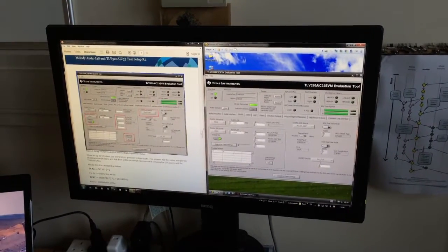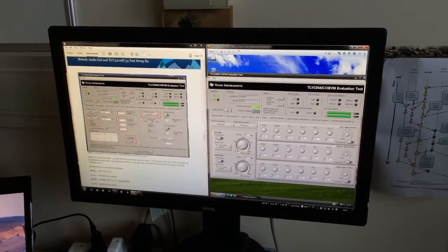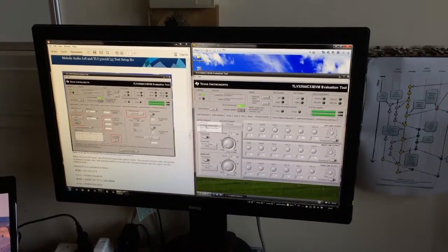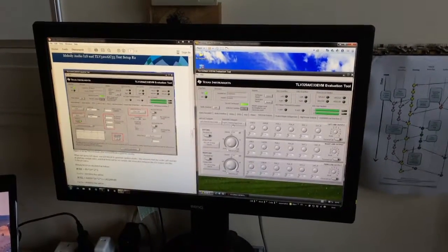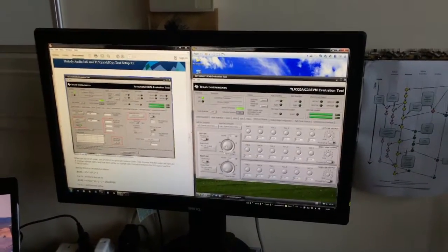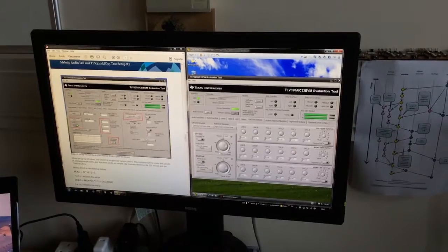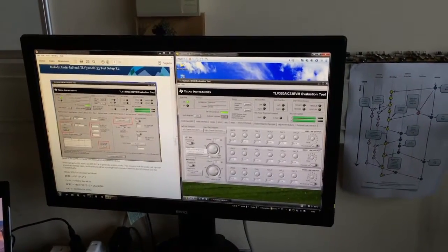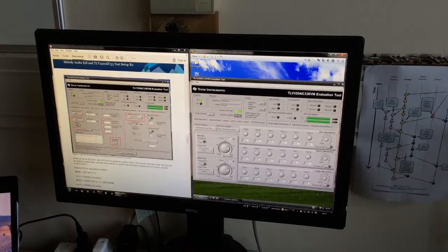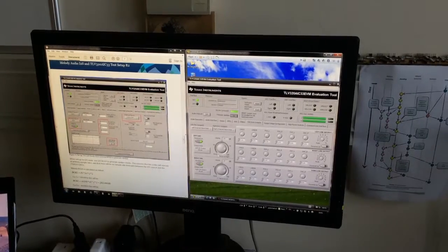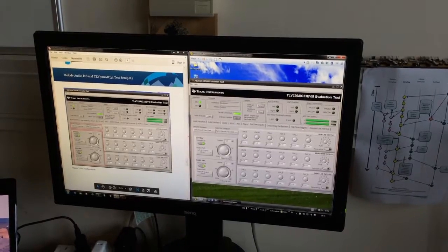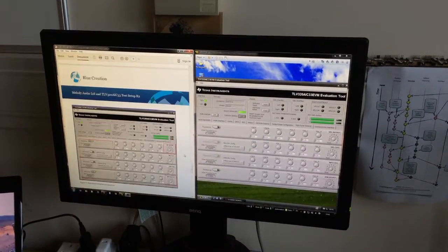Apply those settings. The next thing we need to set up is we need to enable the DACs, and we need to feed some information into the DAC. So the left DAC is going to get the left channel input, the right DAC is going to get the right channel input. I'm going to slave the two gain levels, and I'm going to just put it to some positive value. Select the output path to left high power output driver on both. Then enable both. That enables the DACs, and we can now go to the high power outputs and configure those.